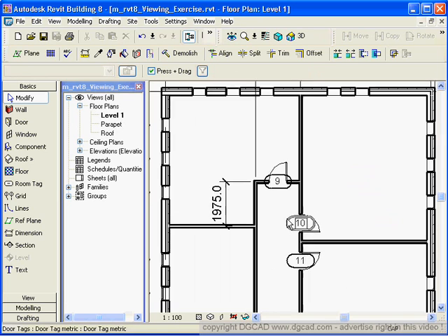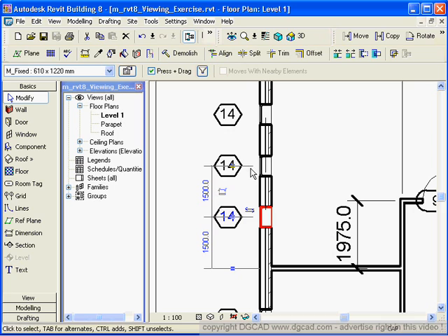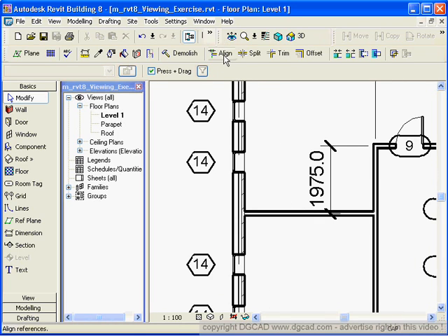Okay, so as you're selecting objects at any point, I can click on here and I can say, okay, well, I want to know the distance from here to here or here, and then you can hit your tab button and it'll actually toggle through the surfaces in the area, and then I can go and change that number to be whatever I want, and then after I'm done I can lock it. Okay, so then you can lock those dimensions.